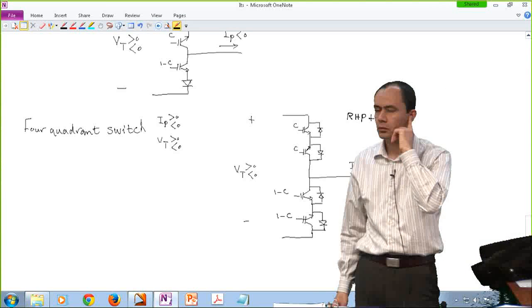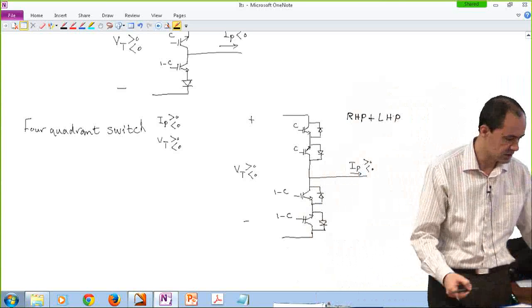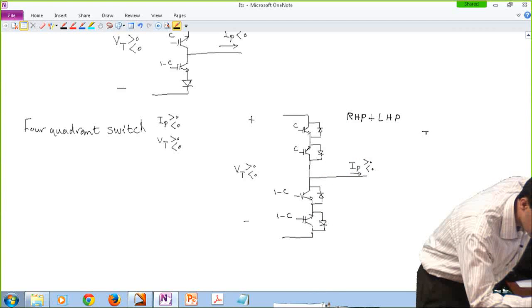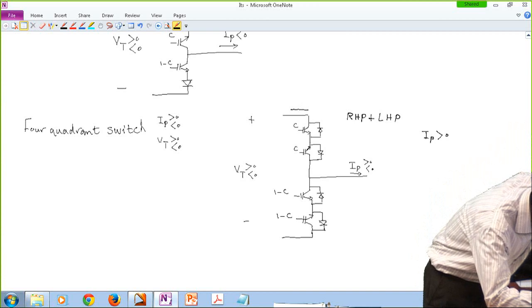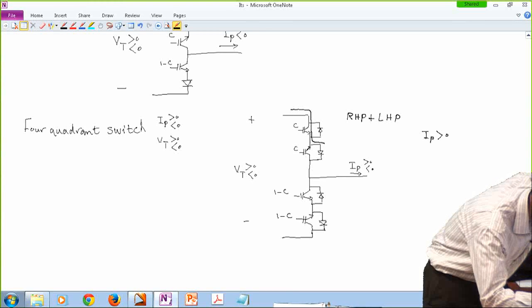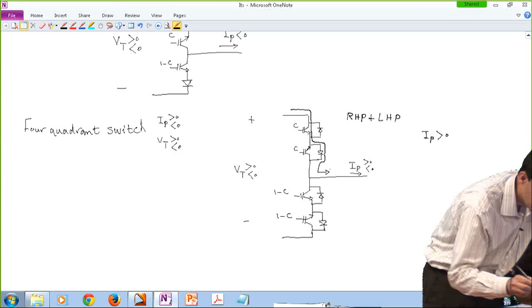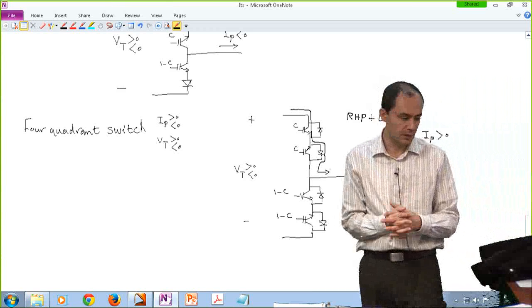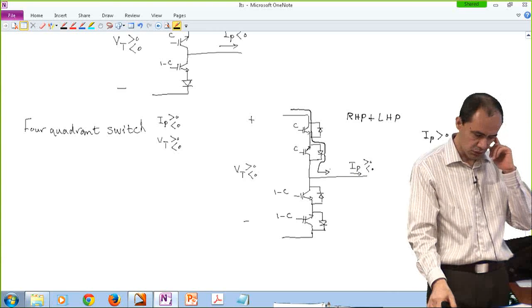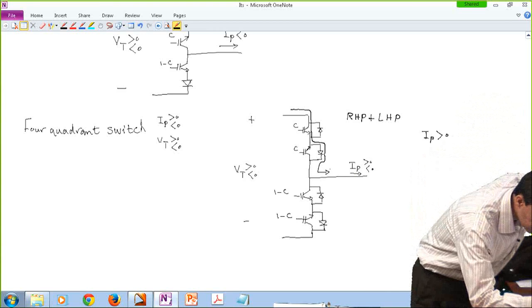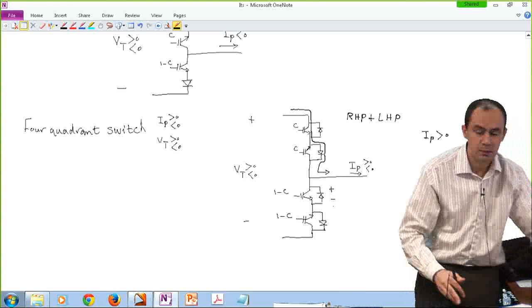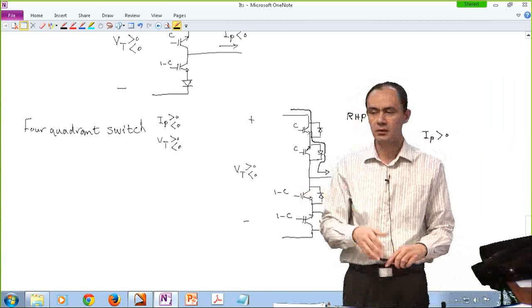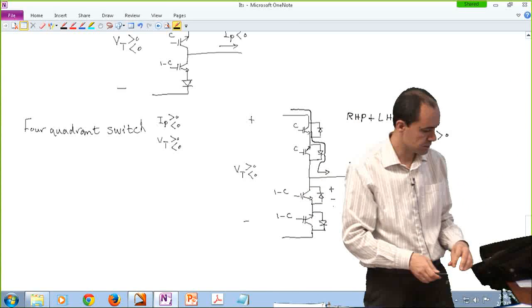All right. So let's look at a couple of scenarios. For instance, let's look at one scenario where the pole current is positive and we want the top throw to be engaged. So basically what happens is we turn this transistor on and we turn this diode on, and there you go. They're actually conducting, no problem there. And then, for instance, if throw voltage is positive, then this diode is blocking the voltage, and no problem there. So the bottom throw is okay. The bottom throw is off, but we've got to make sure it can handle positive voltages.